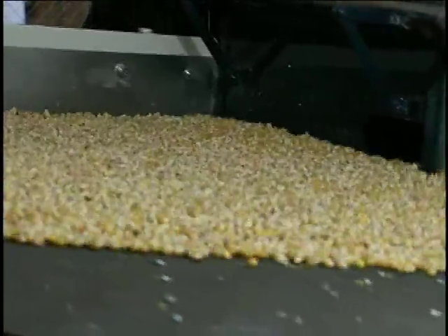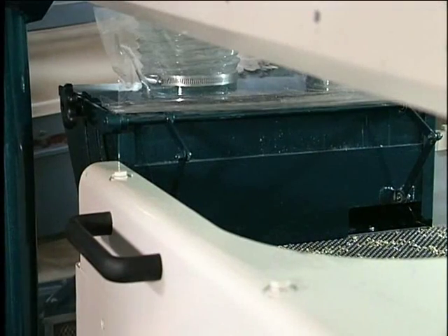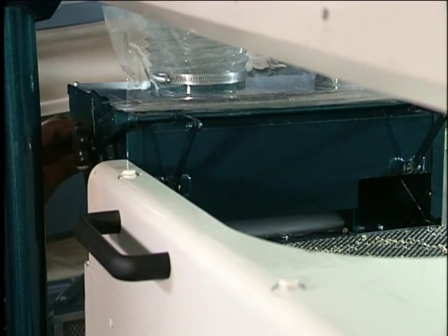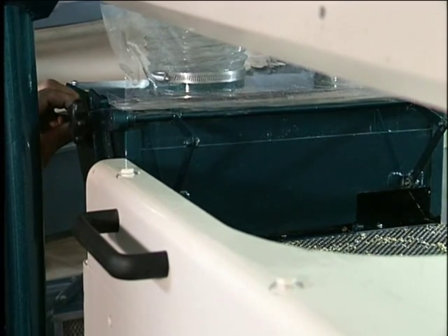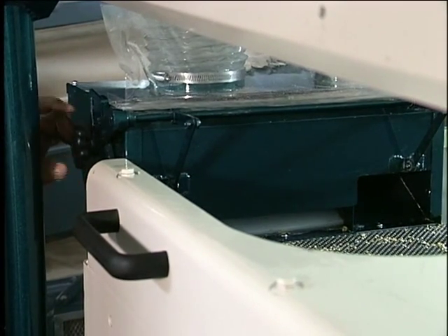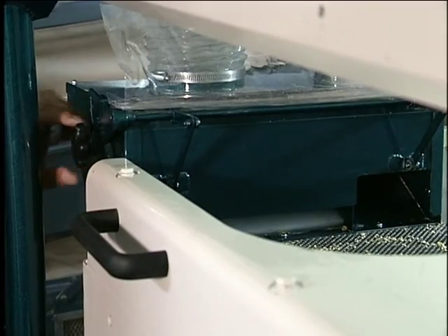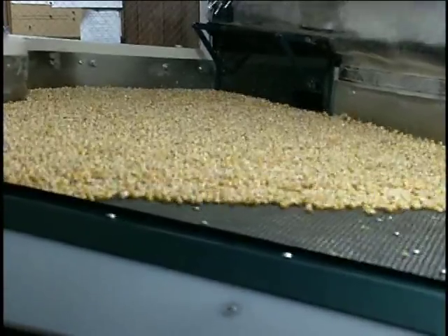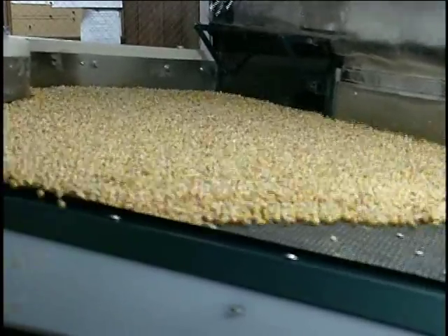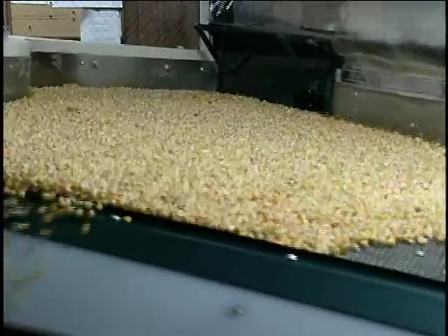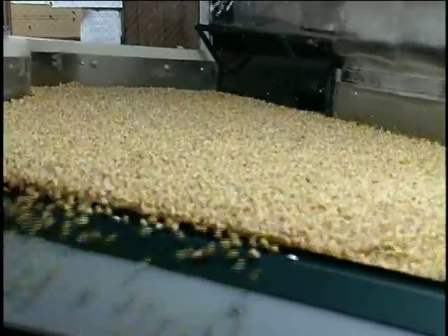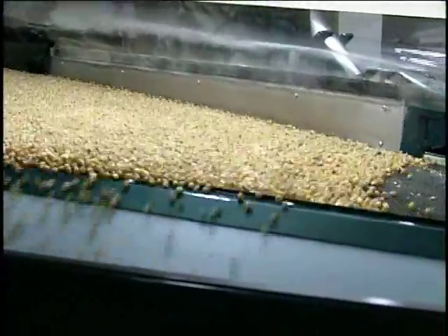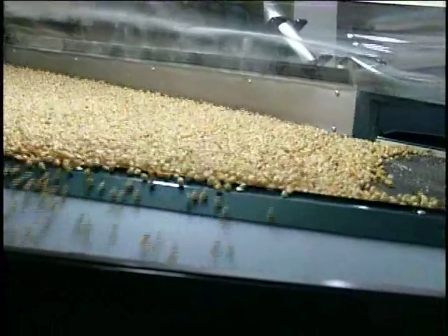A manually adjustable slide gate regulates the rate of product delivery onto the deck. To adjust the rate, loosen the clamping knob and move the gate up or down until achieving the desired rate. Retighten the knob to lock the gate at this rate. It is best to start with a lower flow rate and then gradually increase the rate until achieving your target. With practice, you will learn to recognize conditions on the deck that indicate flow rates that are either too fast or too slow. This topic will be covered in a later chapter.